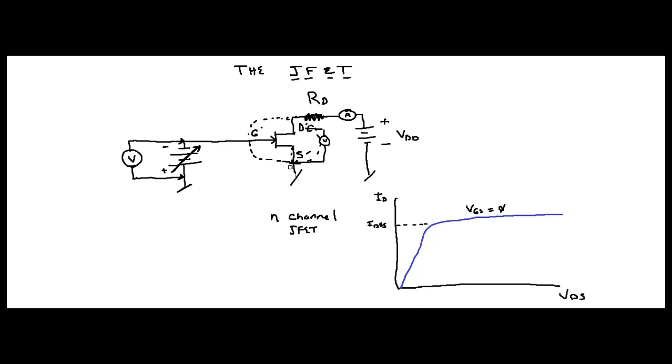So, just cleaning this up for you a little bit. Now, I drew here below VDS, not VGS, VDS, and I drew ID. I created a chart with them. So here's your ID, and here's your VDS. And at VGS equals 0, this is what your curve looks like. Now I only drew it up to breakdown. I'm just looking at the active region.